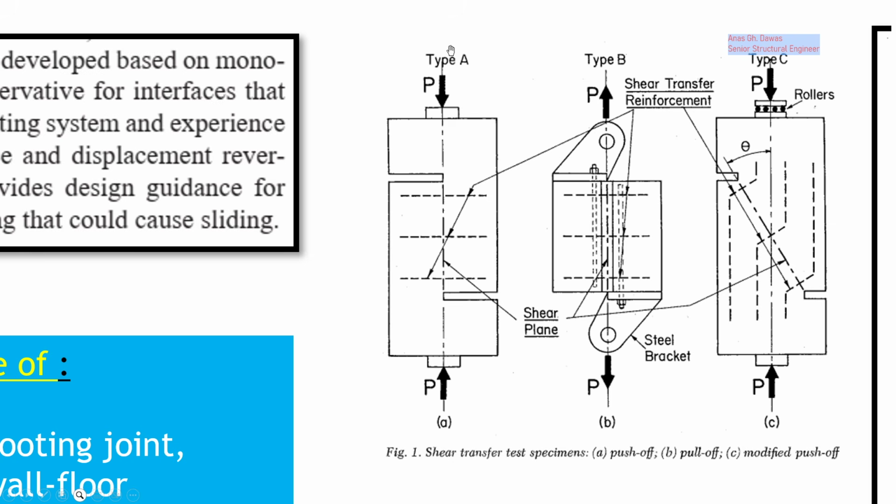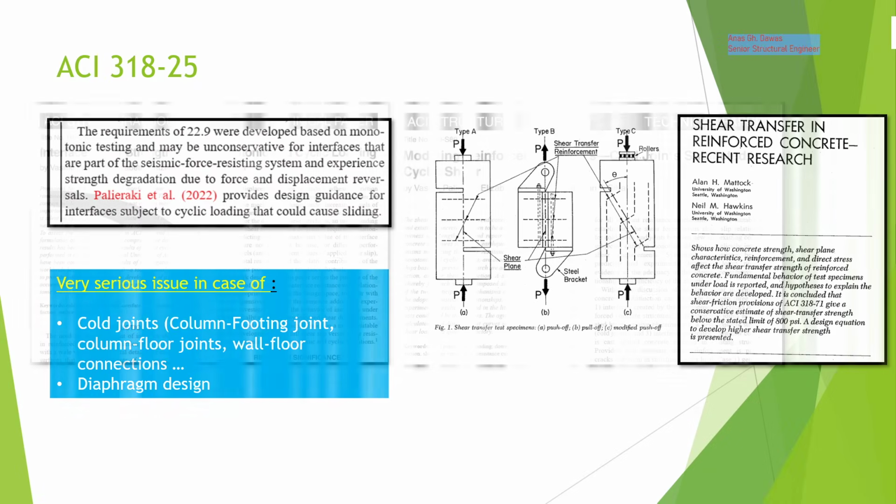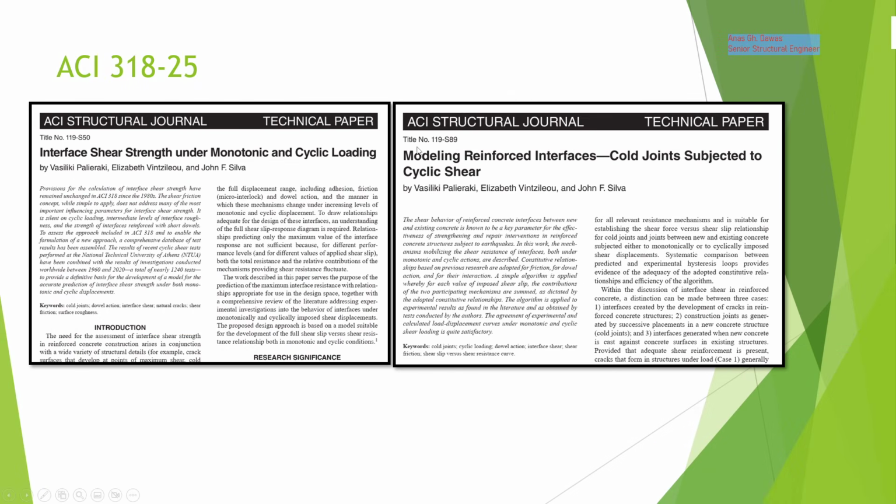So even if you are applying a shear force on those bars, you have to know that the forces developed inside these bars are tension, not shear. So you always have to satisfy the development length in tension on each side of the expected shear failure plane. You can refer to these ACI Structural Journals.